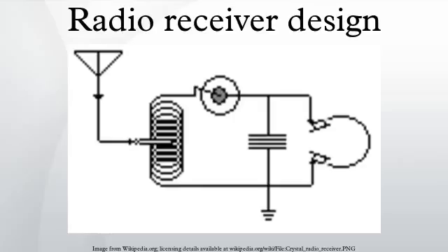earlier FM receivers. For single conversion superheterodyne AM receivers designed for medium wave, the IF is commonly 455 kHz. Most superheterodyne receivers designed for broadcast FM use an IF of 10.7 MHz. TV receivers often use intermediate frequencies of about 40 MHz. Some modern multi-band receivers actually convert lower frequency bands first to a much higher frequency, after which a second mixer with a tunable local oscillator and a second IF stage process the signal as above.